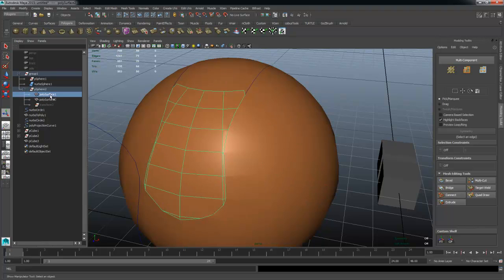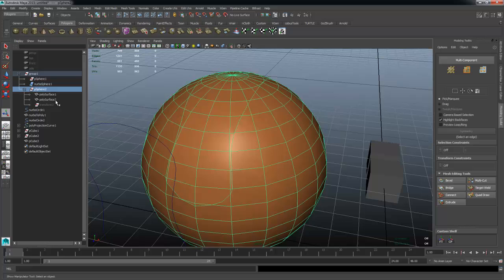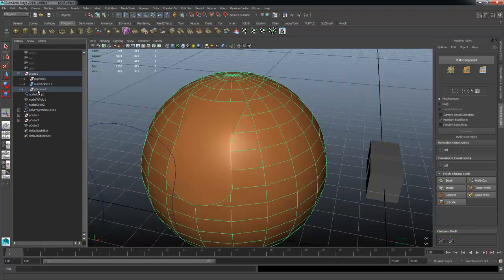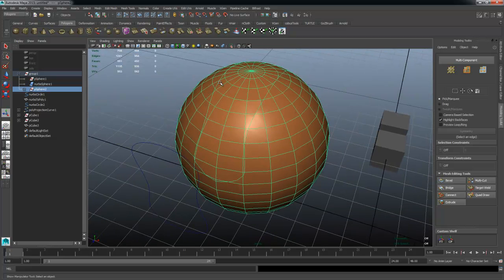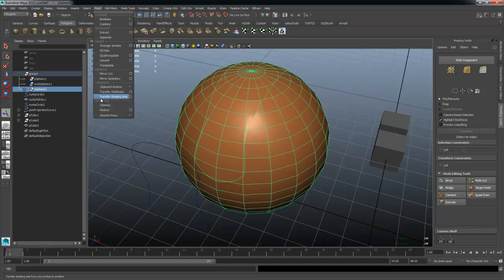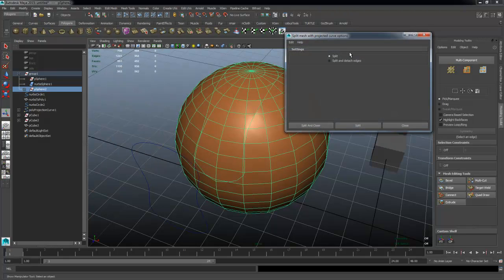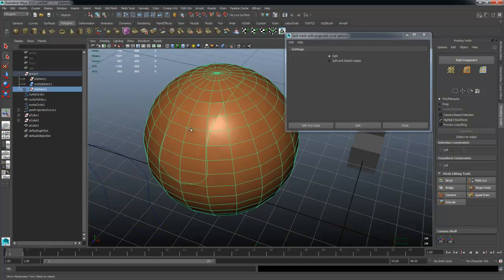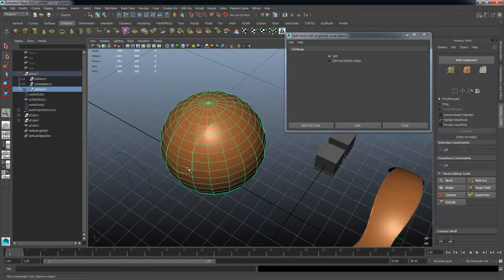And then these are both combined by one transform node, which is the original object, but they're now two separate components for you to manipulate. The only thing that I want to explain to you guys: by going through this process, I've managed to project this curve onto a polygon mesh. But now when I do Edit Mesh, Split Mesh with Projected Curve, the split option is only separating or adding those cuts along the model. It's not making it a separate model like what we have over here.